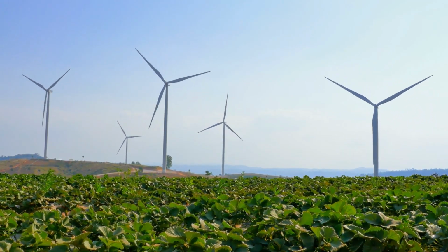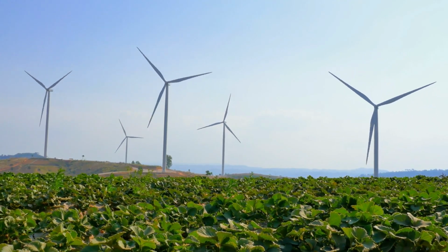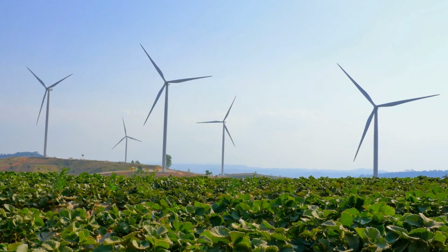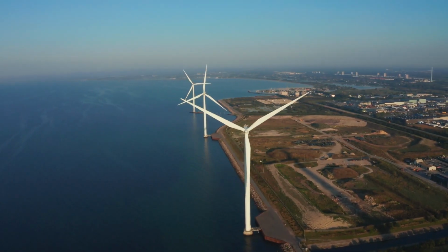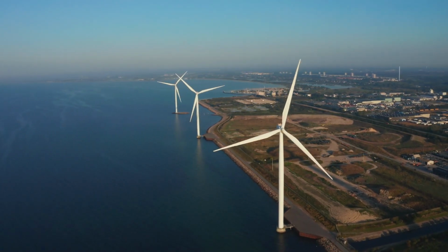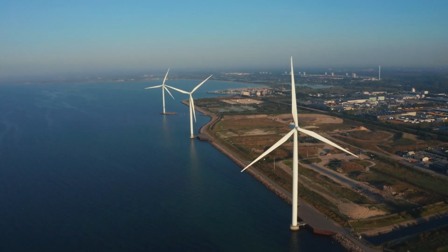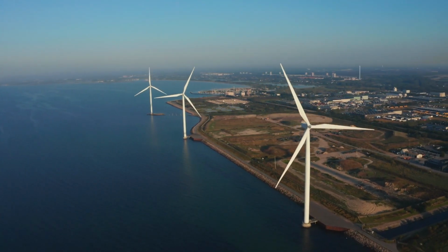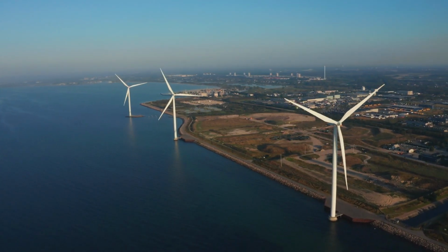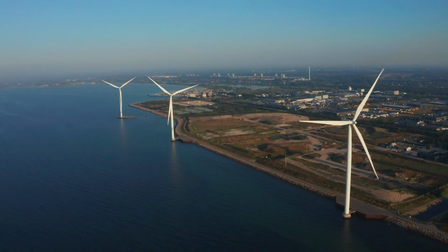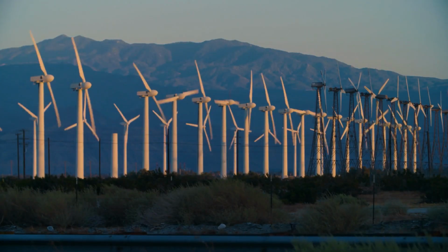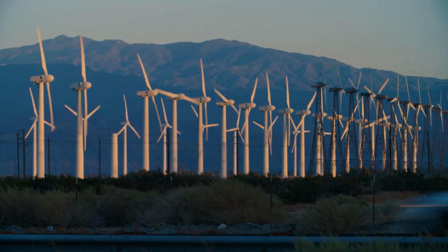It is similar to the wind that blows on an airplane's wing, and by that creates a lift force that pushes the wing up. The wing loses kinetic movement energy that is converted into rotation energy of the turbine blades. The amount of energy produced by the turbine is relative to the thrust area of the turbine blades. It means that the longer the turbine blades are, the more energy the turbine will produce. In addition, the faster the wind speed is, the more energy the turbine will produce.